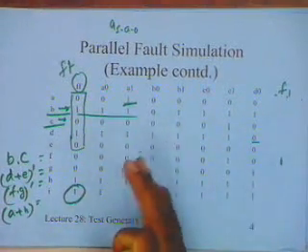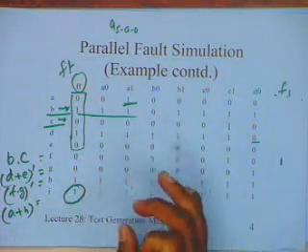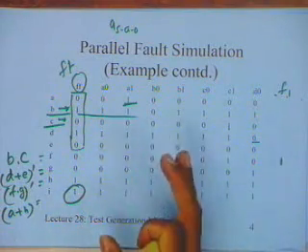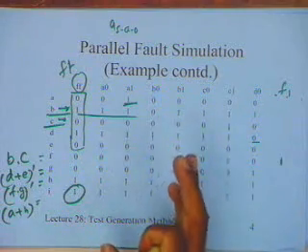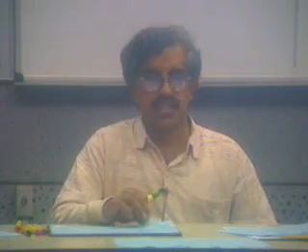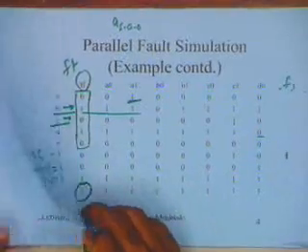It is very clear that all this testing can be done much before you fabricate the first circuit. That is very important. Everything is being done at the simulation level, when only the design of your circuit is present, because you need to do the test vector generation before your circuit is actually implemented, and then you will use these test vectors to test whether the circuit is functioning properly.